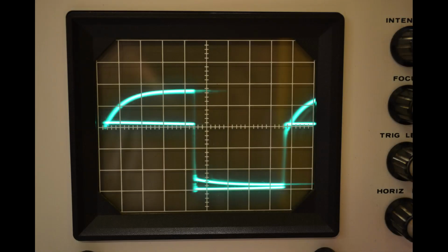At first, I'm concerned that the rise time from 3.3 volts to 5 volts is pretty slow, but again, it's really only about 1.5 microseconds. Most instructions on the 6502 take at least 2 microseconds, and I need several instructions to grab the data, so I've got plenty of time for the signal to settle.